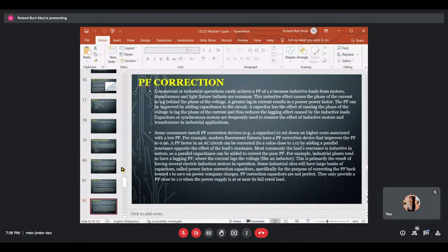A higher PF at the motor means more of the supplied energy will be transferred into usable work by the electrical system. In contrast, a low PF means the current flowing through electrical system components is higher than necessary to do the required work, which is an inefficient use of power.